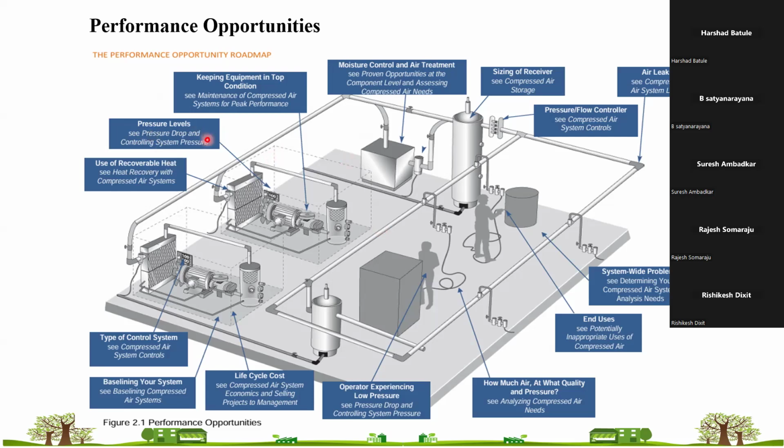Then Sir, is it possible to recover the heat from this air cooled compressor? Because it already has a heat exchanger that is air cooled. So, is it possible to recover? Yes, it is possible, but not from the air, from the oil cooler. Okay.